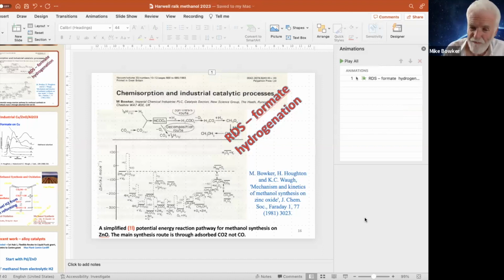But for a roughly 50% copper loading CZA catalyst, the copper catalyst is much better. It reaches equilibrium quicker than the palladium type of catalysts do. So I don't think this is really practically applicable. The only thing I would say in terms of practice is that we have tested these catalysts in an industrial environment, and they are very, very stable. And if anything, more stable than CZA catalysts in a water environment.